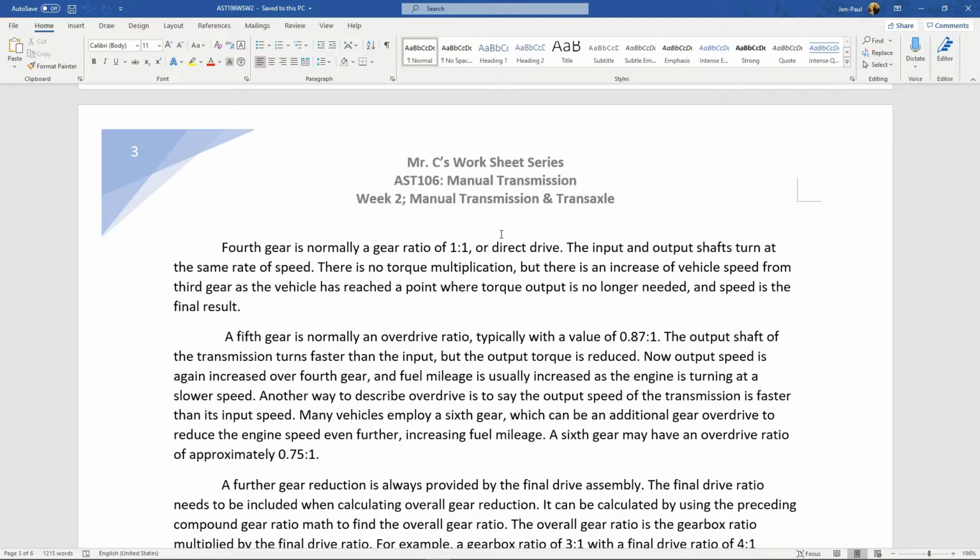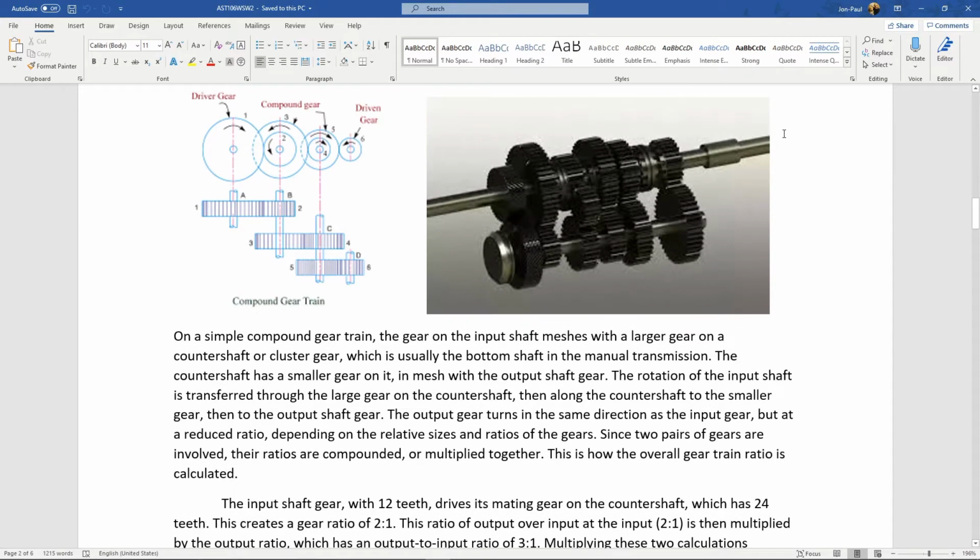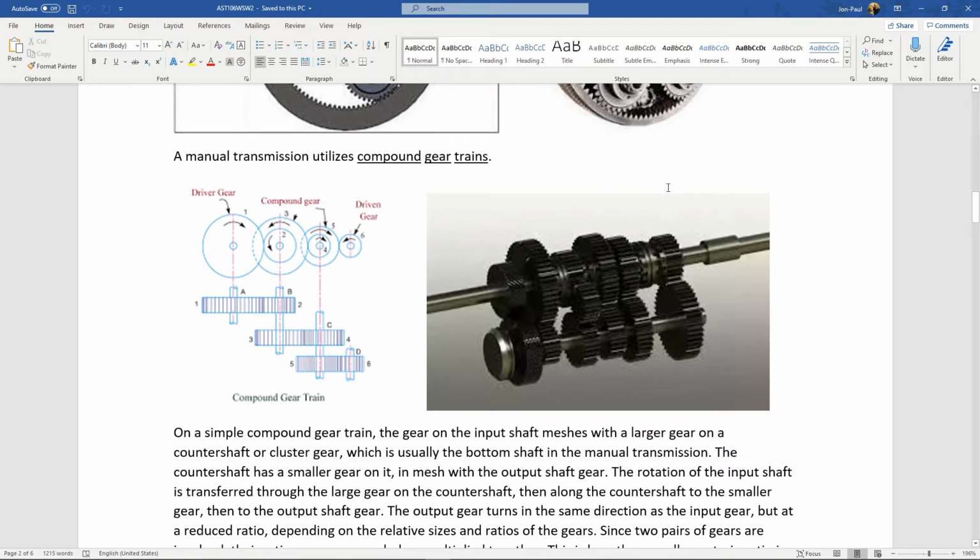Also, if we change the tire and wheel size, you know that on a lot of vehicles the speedometer will be wrong. Well, of course it is. It was working off of the output shaft here. Most vehicles use the output shaft to determine vehicle speed. And it knows the math because an engineer made it, and they know the gear ratio in the final drive is whatever. And the vehicle came equipped with 16-inch wheels with modest tires.